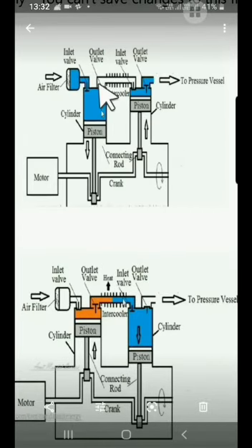At one end of the intercooler it is hot, at the other end it becomes cold. At the same time, when the low pressure cylinder is compressing the air, the high pressure cylinder is sucking the cold air coming out from the other end of the intercooler. Because this is a steady flow process, both pistons move simultaneously.